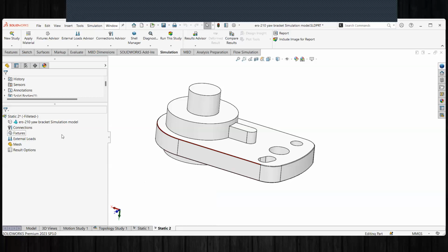All right, so setting up a simulation study. You basically set this up with different folders, just like you would with SolidWorks in general. Whenever you add a piece of work or a feature, it'll show up nested under its corresponding folder. So the way I approach a setup with simulation is I like to start from top and just work my way down from top to bottom. So I'm going to start off here with the material. If your CAD model had already assigned a material, it'll go in and bring that in, whatever that material definition was during the initial creation of the sim study.